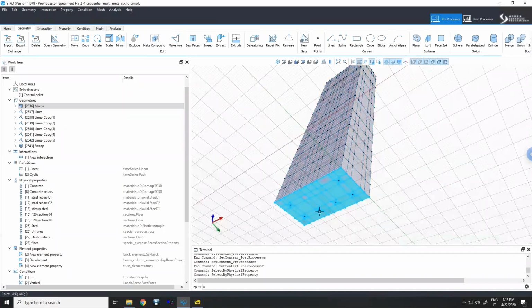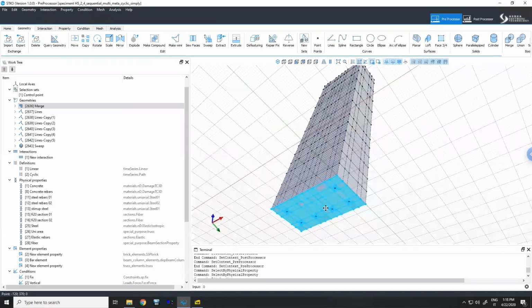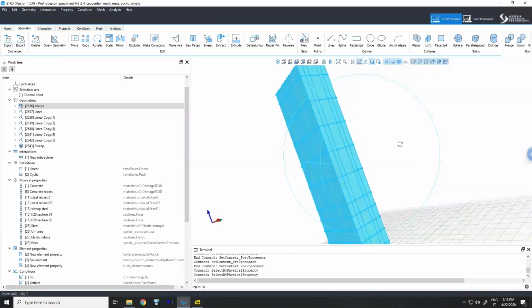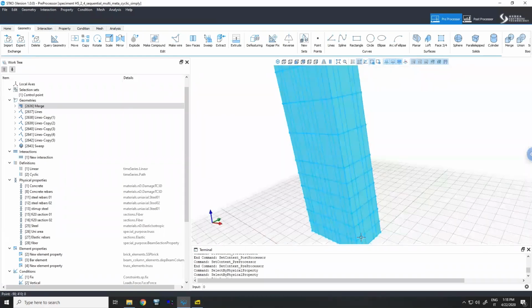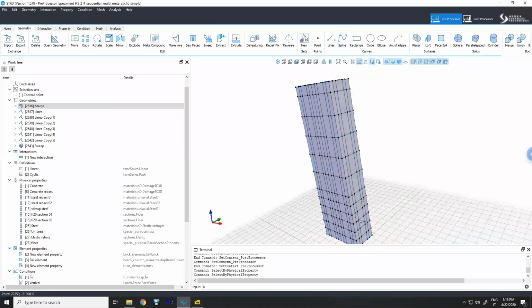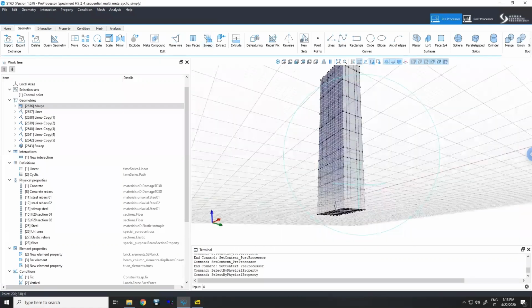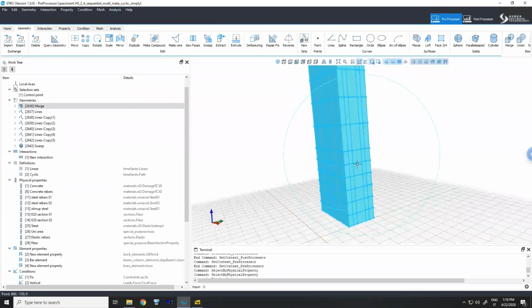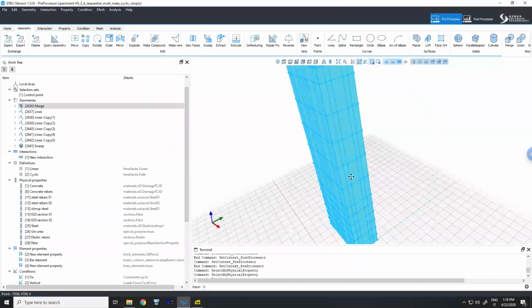And of course, when you have a basic face like this and you want to extrude it, in this case, I wanted to extrude according to the stirrups spacing. There is a specific command where basically you draw the extrusion line and then you do the sweep command. This sweep command will extrude this face along the sweep line. So you have all the correct solids modeled.